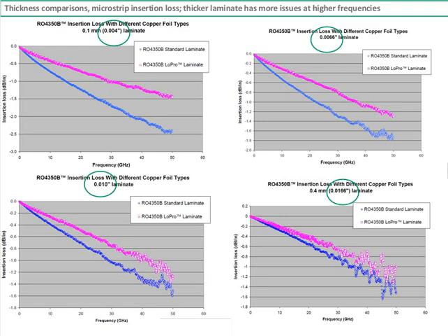But also, as you look at these charts going to the right, that's a little bit thicker, about 6.6 mils thick, bottom left 10 mils thick, bottom right 16.6 mils thick. And you can see as you go thicker, the benefit of going from rough copper to smooth copper is less. So again, thinner circuits are more dominated by conductor effects. So going from rough copper to smooth copper on the upper left-hand chart, you can see a pretty good benefit there.